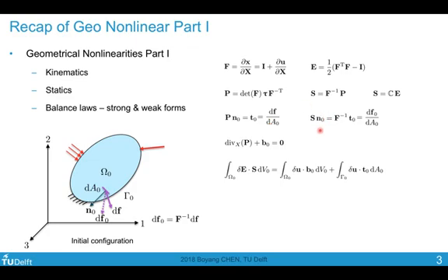While for the second Piola-Kirchhoff stress, its product with the surface normal in the initial configuration gives us sort of a pullback traction, so it's not the engineering stress, and this quantity equals dF0 over dA0, where dF0 is a pullback of dF. And I said that this is an artificial force, an imagined quantity to facilitate the development of this second Piola-Kirchhoff stress tensor.